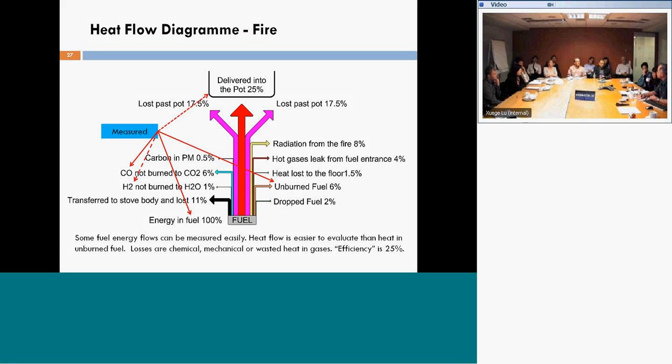A lot of people have been reporting the heat transfer efficiency. My early interest in investigating stove testing was that stoves were being developed which were not foreseen by the early designers of the test, and they were getting outrageously good performance when clearly they didn't have it. I started to look into how can that be, where does it come from? So the calculations that are done, and my careful explanation of the overall thermal efficiency or the system efficiency, matter, because people are being told the efficiency when they're told the heat transfer efficiency. And this is a very big mistake. If you have a stove that is 53% heat transfer efficiency, but only 19% efficiency in taking wood out of the forest, that could be a very significant misguide. I left a slide there to show you that with some calculations, if you had time to read it.